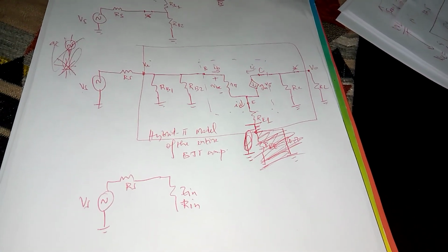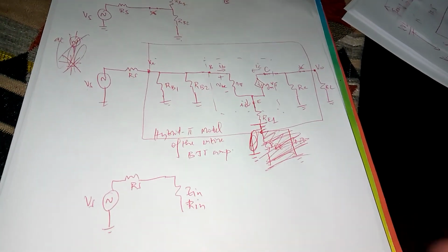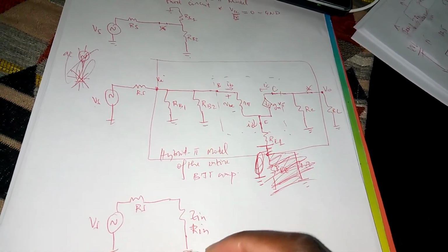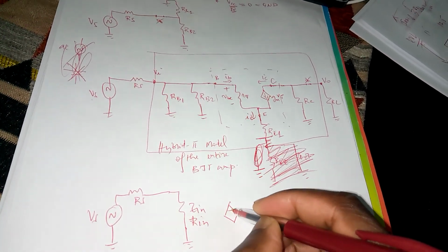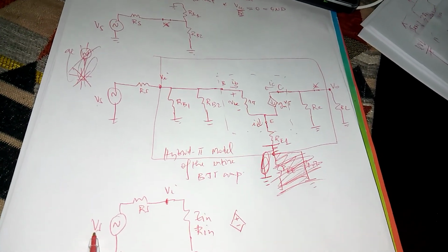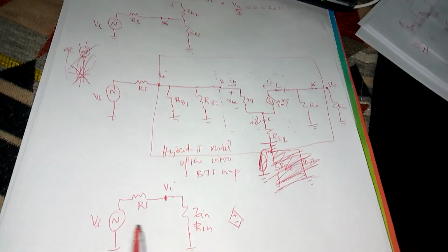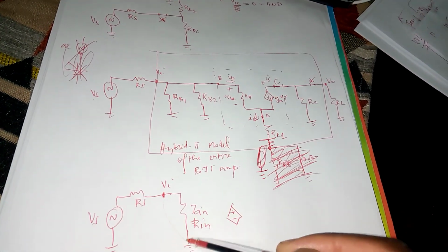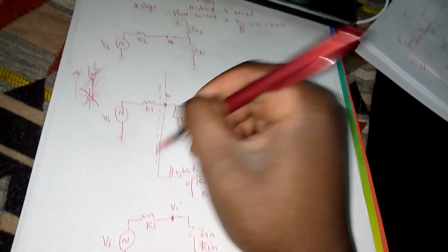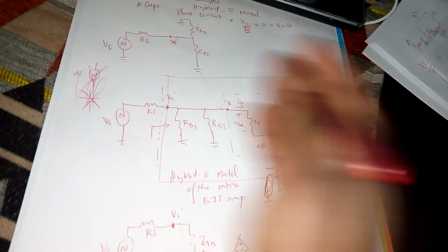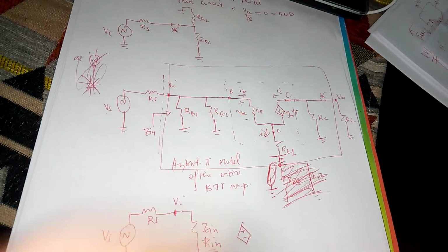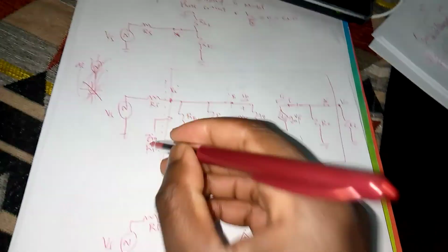Impedance will make much more sense when we start considering capacitors in electronics, but for now, impedance and resistance are all acceptable. Zin, there must be some input resistance, and Vi is there, sharing VS. It's the piece of VS applied on Zin, some input resistance Rin or Zin, which means, going back to small signal analysis to complete it, if you look from that point inward in the amplifier, that's what we call your input impedance, or Zin, also sometimes called Rin, the same thing.